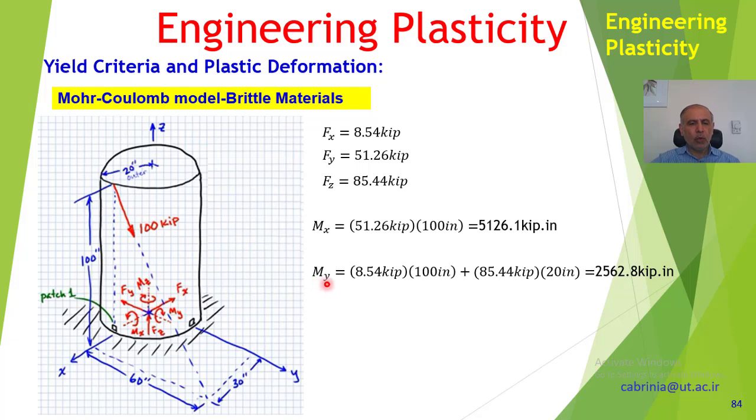And the moment about the y-axis, we have Fx and Fz on this patch, so we have this 8.54 times 100 inches, because that's the 100 inch distance. We want to take it about the patch. So My, look at y, we have this axis y, so we have one component of Fx and one component of Fz.